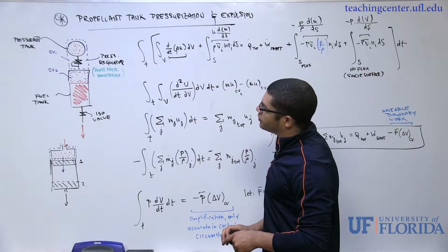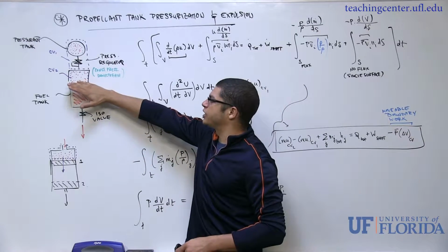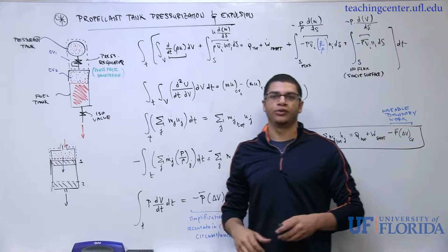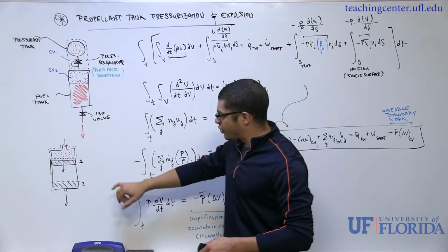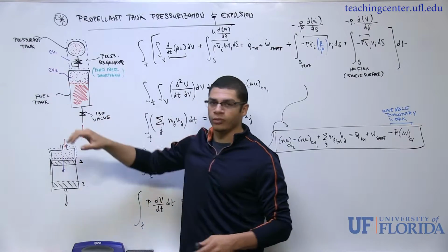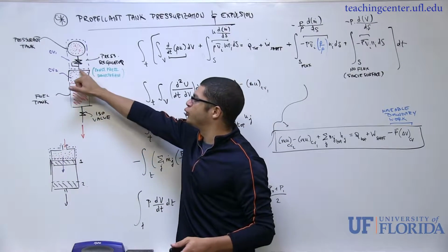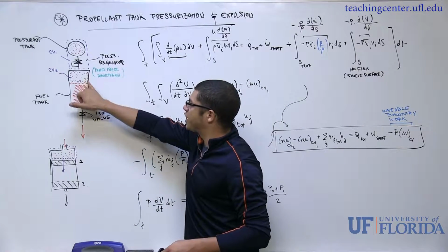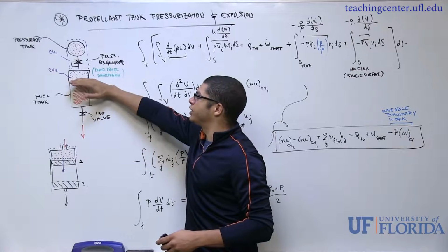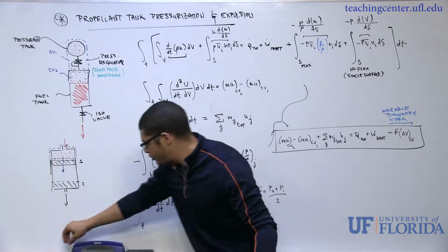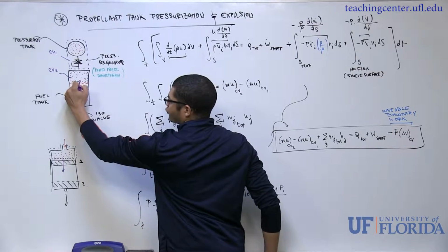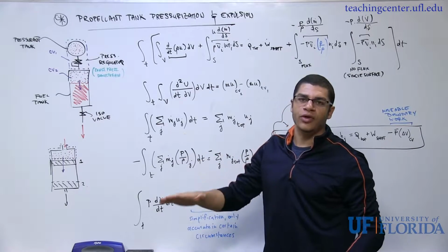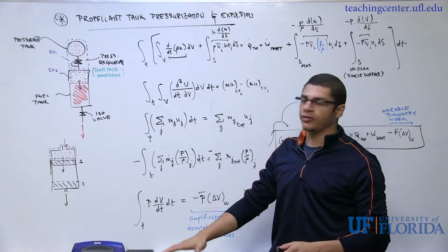Now, one thing to think about here is that when the gas is acting on this liquid, we can translate that into a piston cylinder type of problem. So what I've done is look at CV2, my control volume 2, where I've cut through the pipe in the top of the tank, and the way I've drawn it, it's matched against the walls of the fuel tank. I haven't drawn an arrow here, and I probably should to make it a little more clear, but we're going to assume that the bottom portion of the control volume moves as the liquid level moves. So it's going to move with that interface.